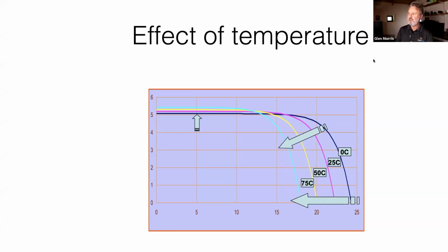Justin's asked, the new battery standard AS/NZS 5139, that's for New Zealand and Australia, protection devices required to have an IP rating of 56, no water. That's correct, Justin. I'm not sure what the question is there, but anyway, that is true.